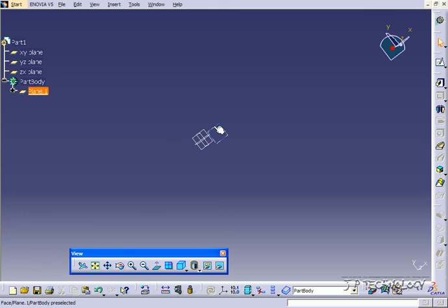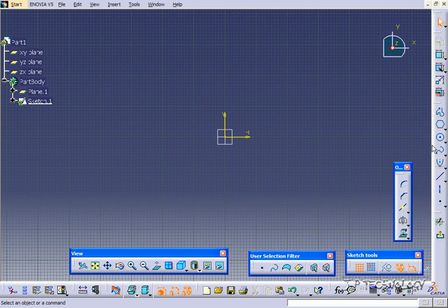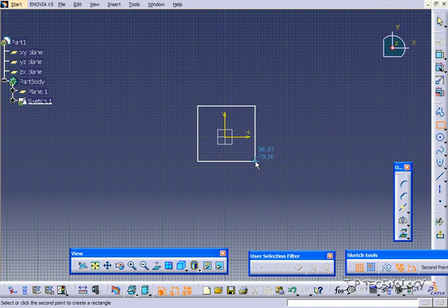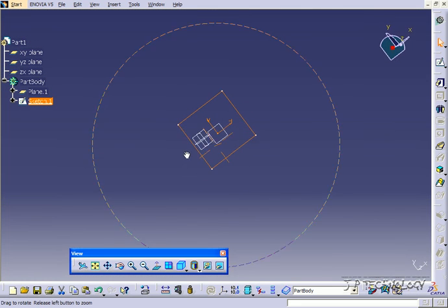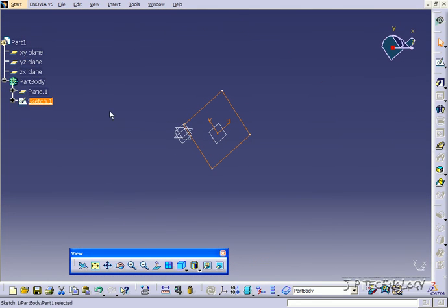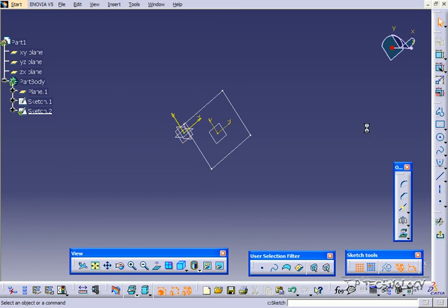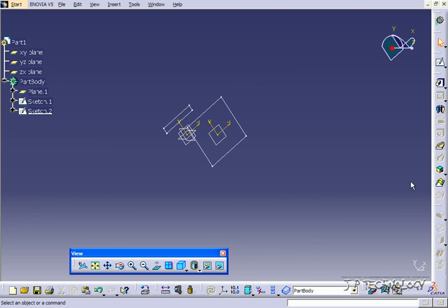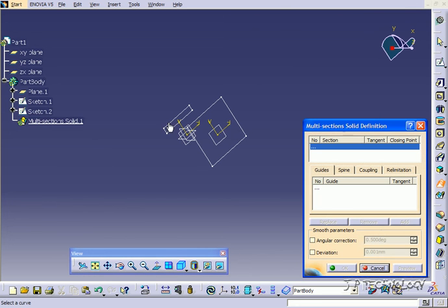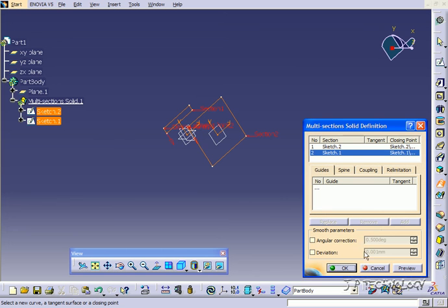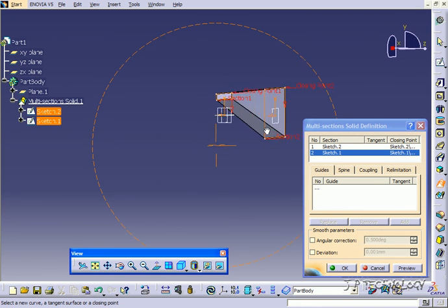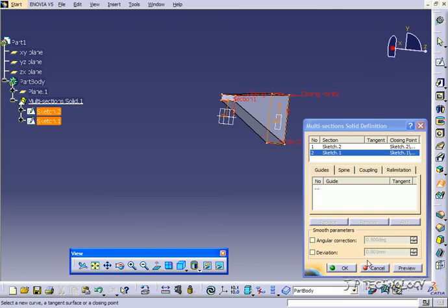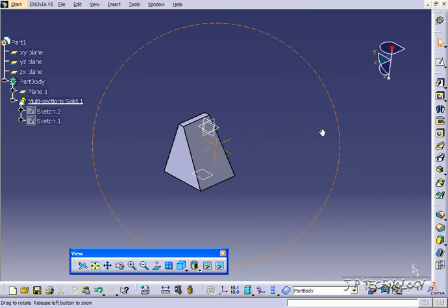And let's click this plane here, click sketch, and draw in just a quick sketch, one that looks like a square, and we'll go out, and on the offset plane to that, the XY, let's click sketch, and draw a thinner one, like a rectangle. Once you have that, go out, and let's do this multi-section again. Click the two sketch profiles, click preview to see what it looks like, and you've got them sweeping together to create a solid. Click OK, and you have your part.